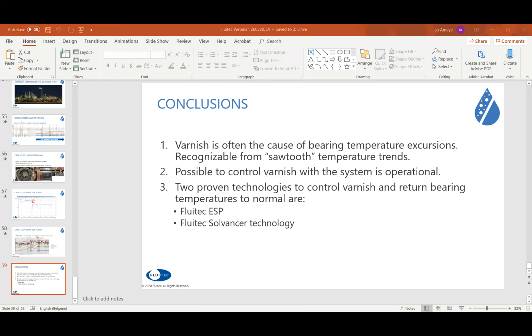Like I said, the definition is that it's mostly organic. It is like a polymerization, agglomeration process. It sticks to the metal surface and you cannot remove it. Sludge is just the opposite. Sludge is more an agglomeration of consumed additives, some antioxidants, EP, reacting with water.